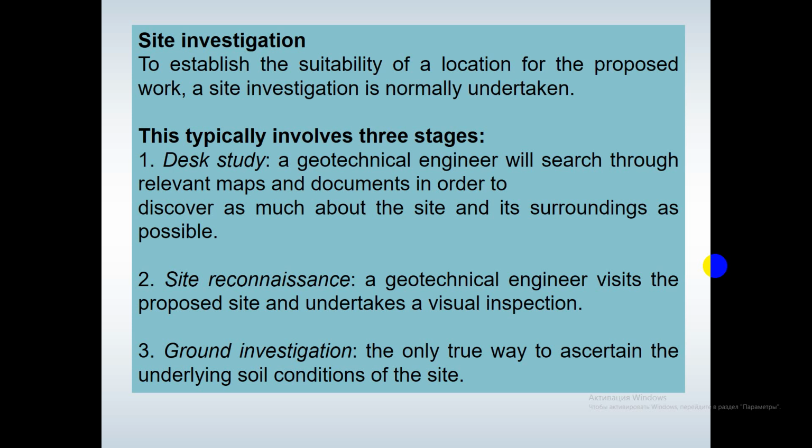The next stage, ground investigation. The only true way to ascertain the underlying soil conditions of the site. During the investigation, accurate information relating to water should be obtained. Suitable soil samples for both visual classification and laboratory testing should be extracted.